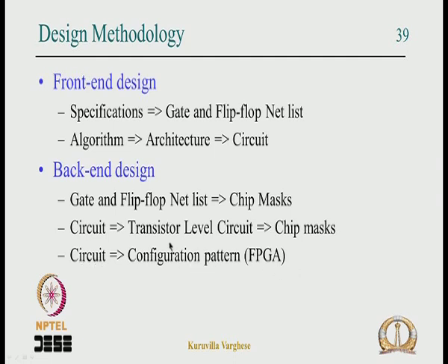So for FPGA this physical synthesis and chip mask is not there. We directly go from this circuit level to the configuration of the FPGA, with of course a step involved in translating this circuit, mapping it to the resources of the FPGA, interconnecting it and so on.